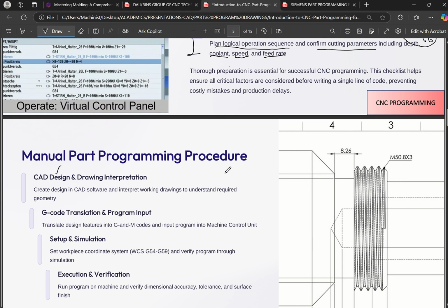You can use CAD design software, let's say like Inventor, SolidWorks, Creo PTC, maybe Fusion 360 or FreeCAD, to design your part. Then that part, if you're designing it for machining, you have to consider all parameters, all tolerances, all surface finish in a simple drawing. Let's say this is a simple drawing you want to send to the shop floor. The person in charge in the workshop, maybe now the part programmer, is able to program and then machine the part. So the first procedure that is very critical is how do you interpret the drawing you have designed